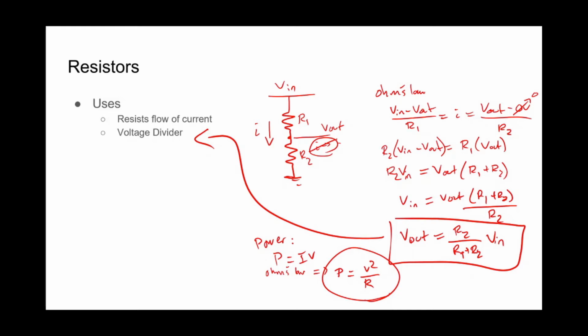All right, I think we've done enough damage on this. We'll come back to applying voltage dividers in just a second, but keep in mind, like I said, you could use this if Vin was variable, like a battery voltage, and you wanted to measure that battery voltage, but you can't actually measure a voltage that high. Like if you wanted to measure a 9-volt battery with an Arduino, it can only measure 5 volts.